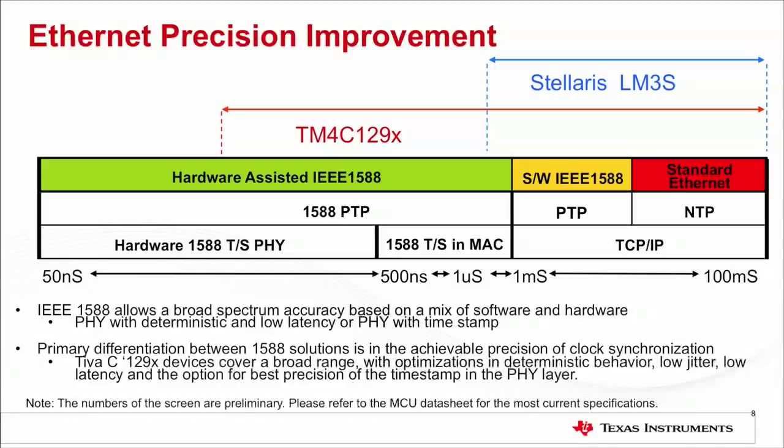It means that the Ethernet controller on TM4C129X devices can be used in applications where the devices with legacy Ethernet controller could not. With the new Ethernet controller, you can now achieve master clock to slave clock synchronizations down to a couple hundred nanoseconds of error. In addition to the much improved synchronization performance, TM4C129X devices have few other tricks under the hood to improve basic Ethernet performance. Let us elaborate on some of those.